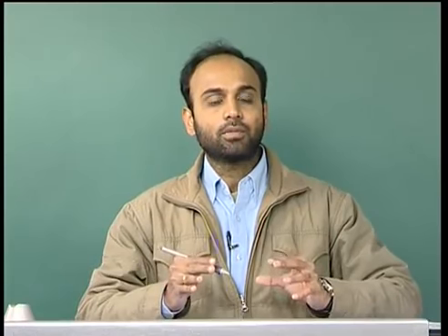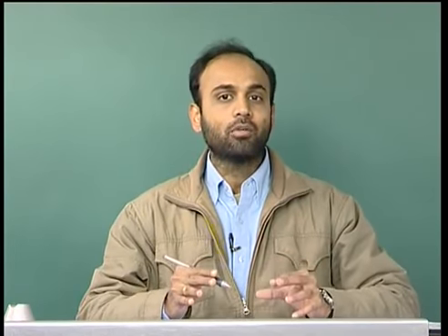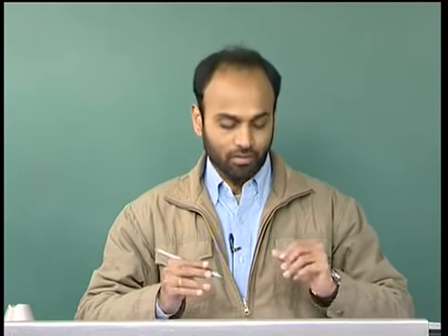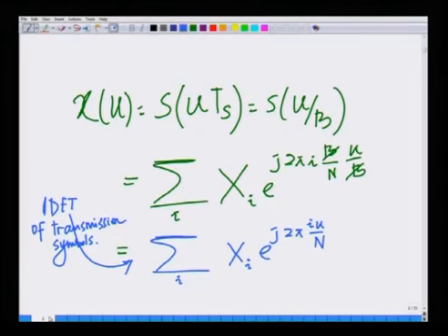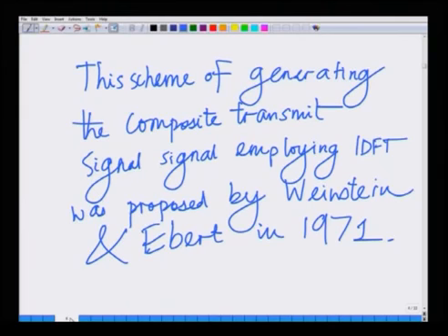Hence, to reduce the complexity, we used an idea proposed by Weinstein and Ebert and successfully replaced that bank of modulators by a sampling operation, which is nothing but an IFFT. Hence, we said that the bank of modulators can be replaced by an IFFT operation. This idea was originally proposed by Weinstein and Ebert in their 1971 paper.